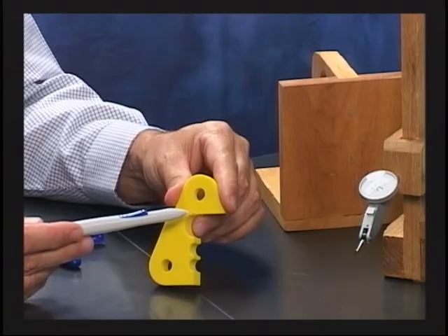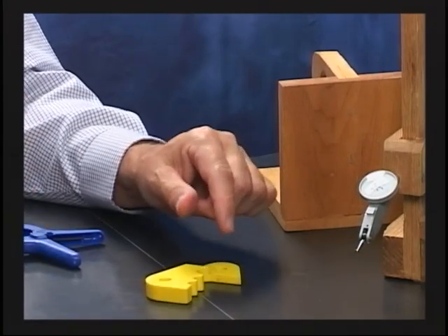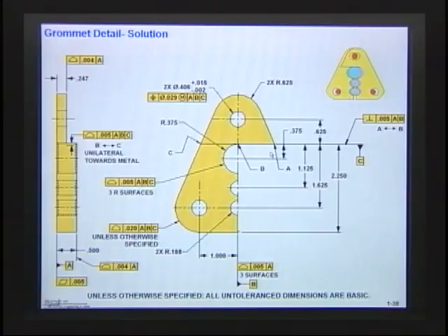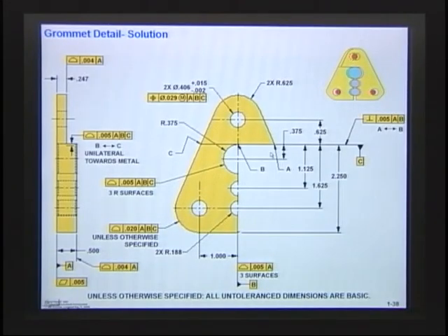Now, just be aware here. Let me show you on our graphic. Let's go back to the graphic for a minute. On the graphic, I'd like to show you some things. If they come in with a coordinate measuring machine and just touch 2 points, you wouldn't know much about that surface. So they would probably have to touch a number of points on that surface. And when they did, they would find out if it fell inside of a tolerance zone, right?